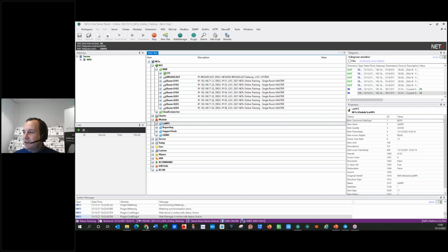So in this second session, we will start explaining different integrations, not only KNX, we have already done it in the first one, but also very important protocols like BACnet or Modbus, for example. With KNX, there are the three big ones in the building automation systems. In Europe and the rest of the world, I think, Modbus maybe is the less used or the oldest of the three, but it's also being used in a lot of projects.